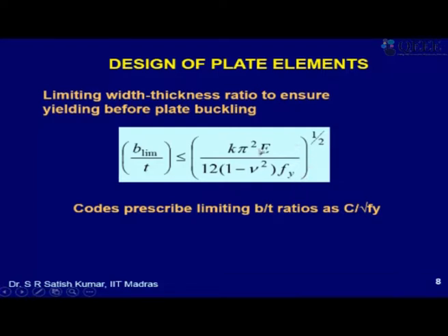And as I said, for any grade of steel, Young's modulus and Poisson's ratio are generally constant. So we can even substitute these numbers, and pi square is also a constant. So for a given support condition, let's say hinged, if I take K as 4, then this entire thing becomes a constant.